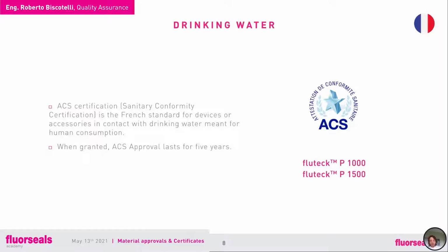Again, as for the NSF, the standard divides the products based on the surface area that comes in contact with water, so the exposed area, and the temperature. They divide the products into 4 classes, from up to 3 square centimeters per liter up to 230 square centimeters per liter. This, as many of the other certifications for drinking water, lasts for 5 years.